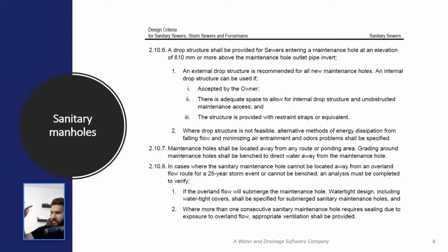So technically, for any overland flow, we should do all our best to locate the sanitary manholes away from the overland flow. However, it is almost impossible on a lot of occasions. So that's why, in the next part,